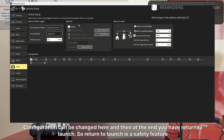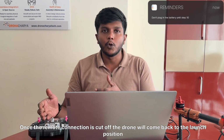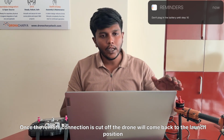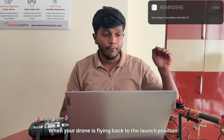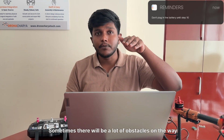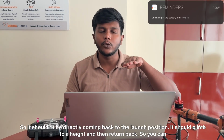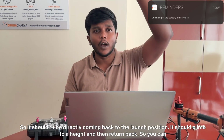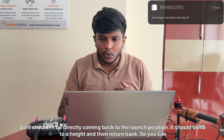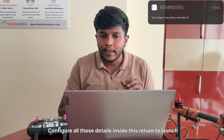And then at the end, you have return to launch. Return to launch is a safety feature where, once the remote connection is cut off, the drone will come back to the launch position. When your drone is flying back to the launch position, sometimes there will be a lot of obstacles on the way. So it shouldn't come directly back to the launch position. It should climb to a height and then return back. So you can configure all those details inside this return to launch setup.